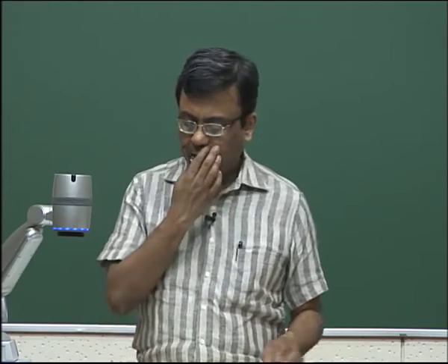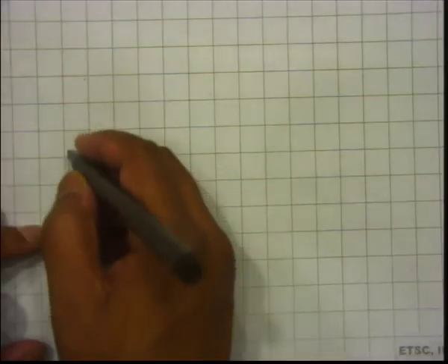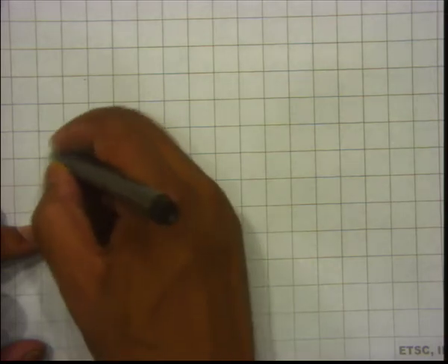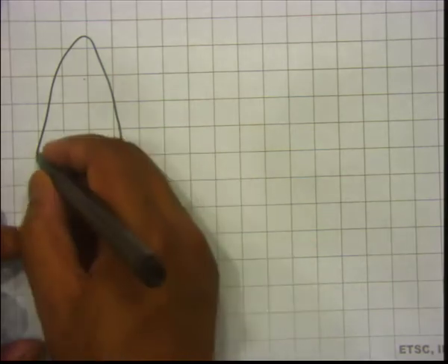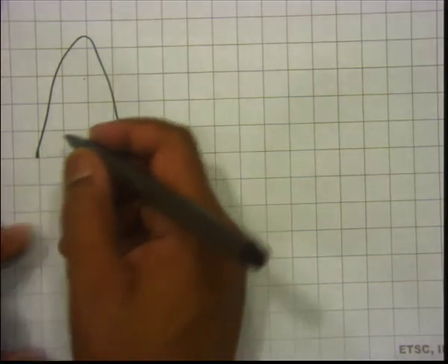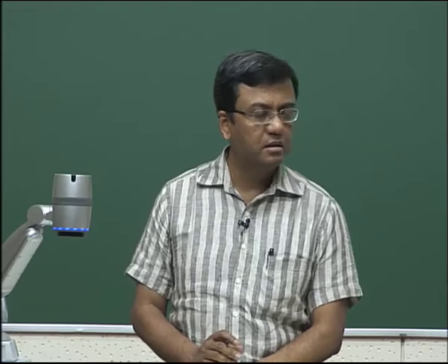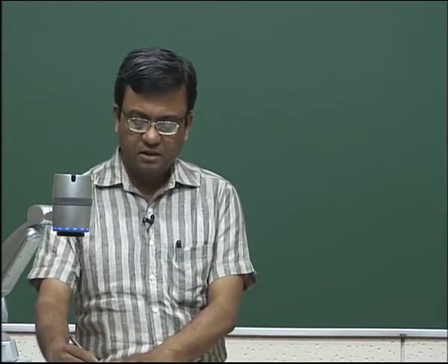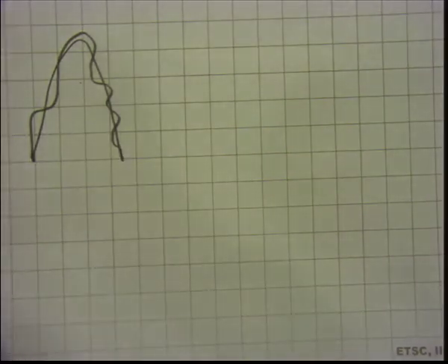Okay, so we have some understanding now, but let us also think about the wrinkled reaction sheet regime to some extent. Now, if you have, for example, a thin flame, which is a laminar kind of flame, and reaction is fast, so it is a thin flame, but now you put in turbulence, then what turbulence does is make the flame wrinkled.